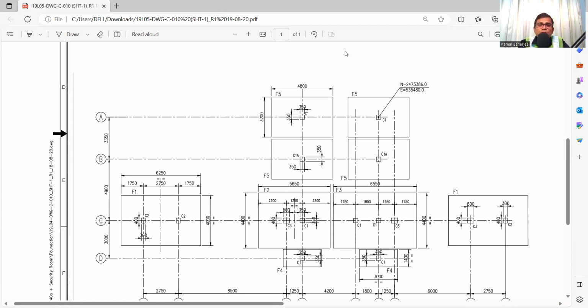So these things you need to take care of whenever you are doing the building foundation. First, you need to find out the grid line or the reference lines, then place the 4 corners, then the center line, then check the squareness by 3, 4, 5 or the diagonal method, then check the inter-distance of the foundation, check the center line distance, and check the adjacent structure distance, and all are to be documented as per the requirement. And after everything, if it is okay and the consultant is giving the approval, you can start the excavation. So these are the things about the building layout or the foundation layout. I hope I covered everything.